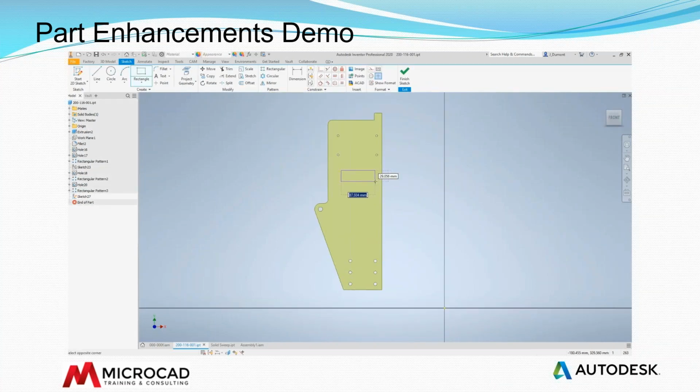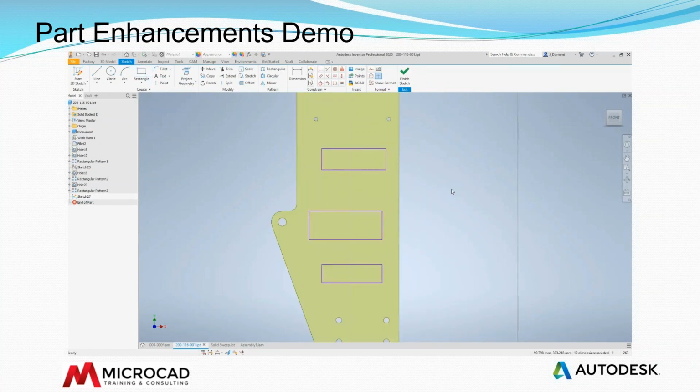I'm going to create several profiles. This is extremely common in one way of geometry, and in a particular workflow, it's easier to relate all of the sketch profiles together, and they might have different properties. One profile might remove material, another one might add material, they might be different height. So instead of creating a separate sketch for each feature, you could have one sketch, relate the geometry together more dynamically, and then work with it in one command by sharing the sketch.